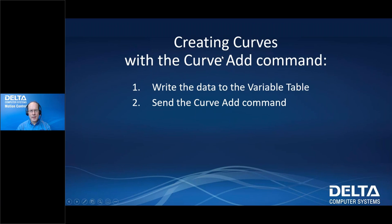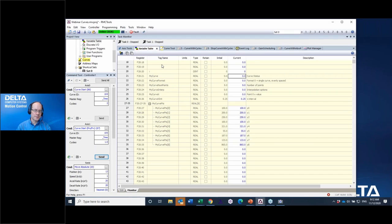So creating curves with the curve add command is not all that difficult, really. Number one, you write the data to the variable table, defining some specific location in there to write it to. And then you send the curve add command to the RMC that tells it to make a curve with that specific data in the variable table. So let's go look at that.